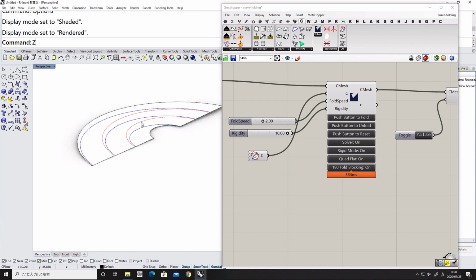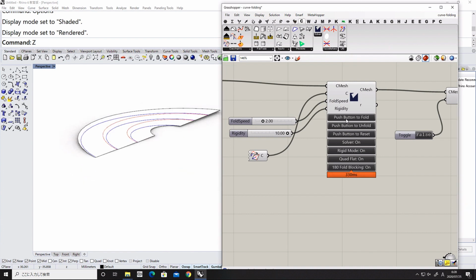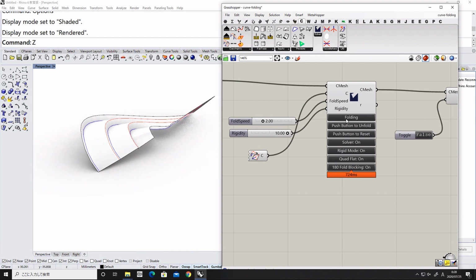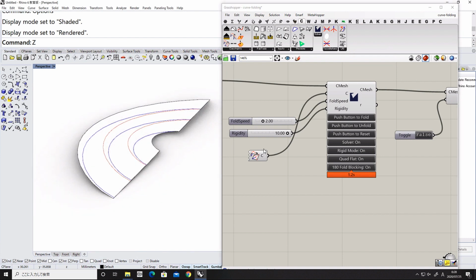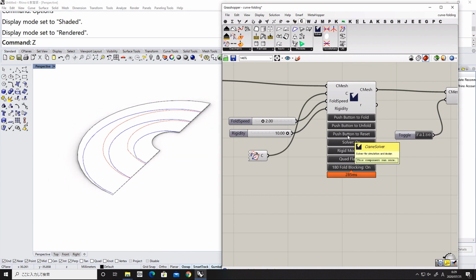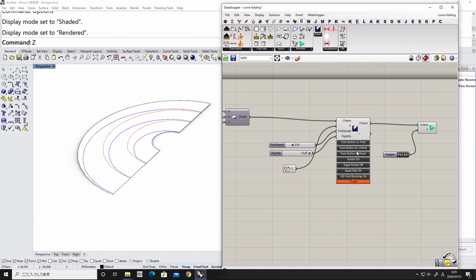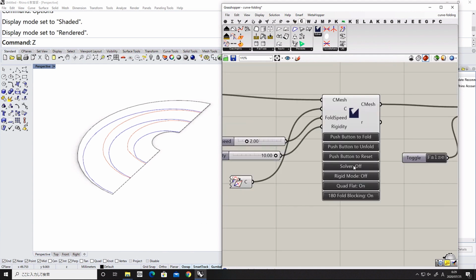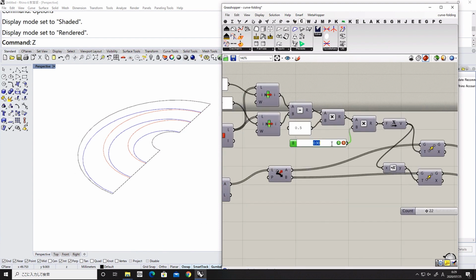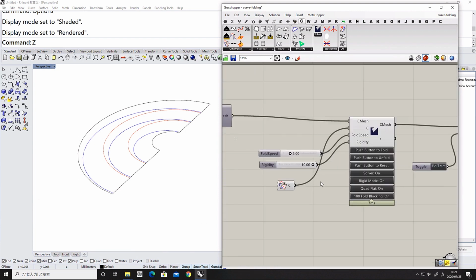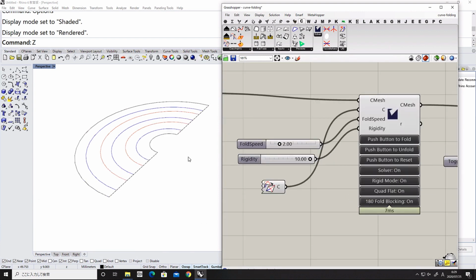And yeah, let's try using developable constraint. This Crane plugin lets you have additional constraints on the geometry that you made in order to create more controlled folding simulations, which is really great. Okay, let's set this to a bit lower value to see the difference.